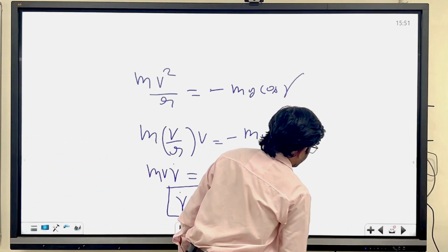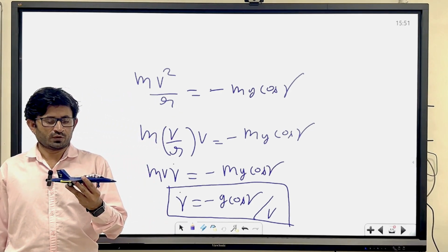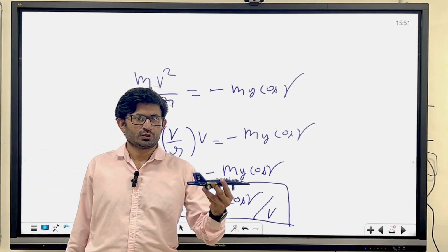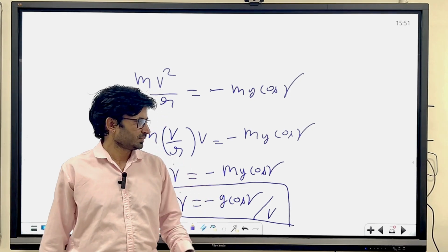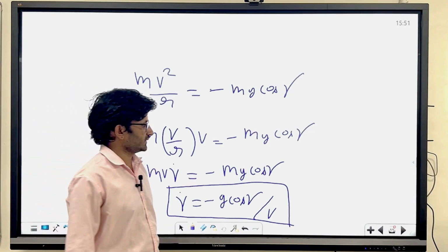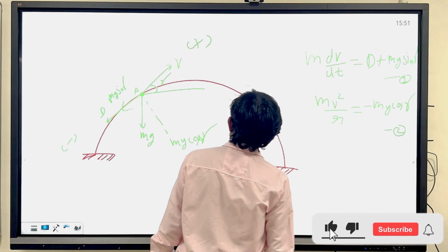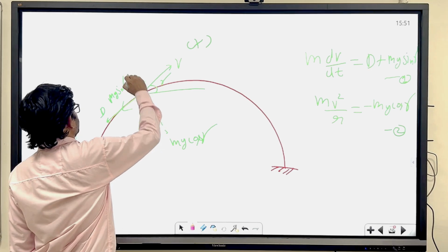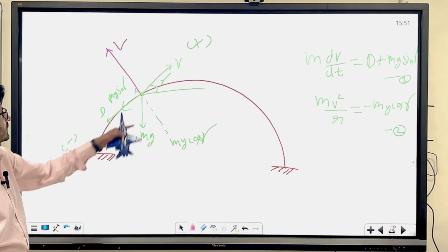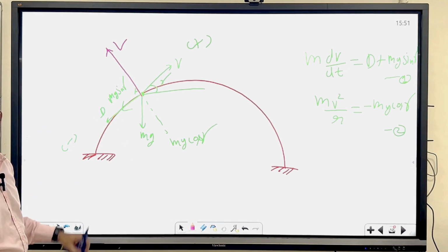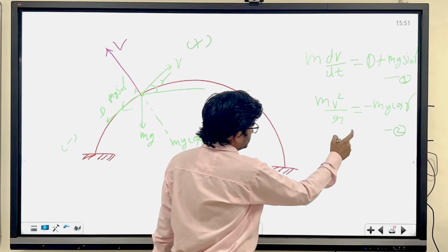Now consider your flight, a steady state level flight. If you are flying at a steady state level flight, your gamma is 0. So somehow you have to make gamma equal to 0, right? But how can you do this? Let's see. If you add lift in this direction, perpendicular to the speed and drag, you can change this equation to this equation.